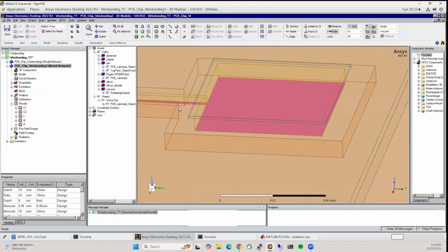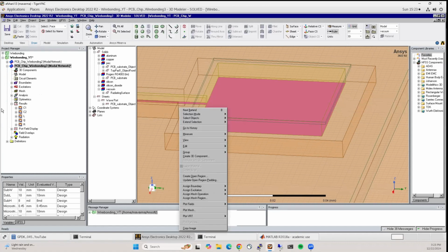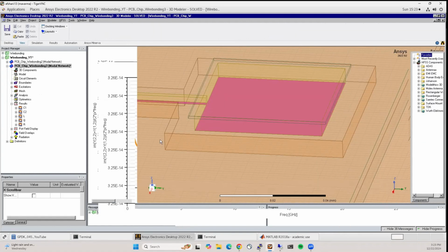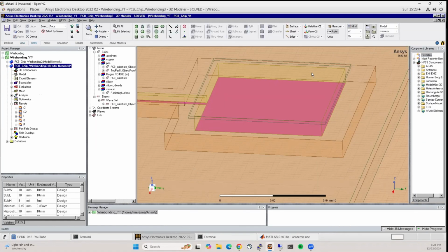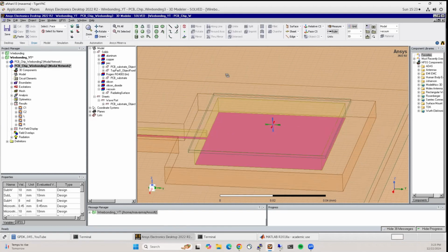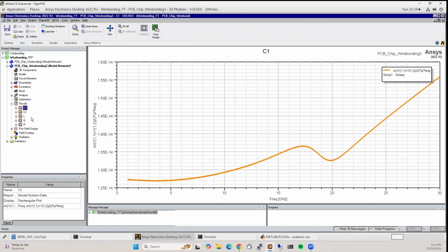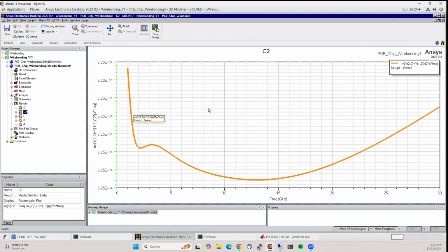Right? And what was the value that we got here? It was around 32. That makes sense, of course, because there's a lot of fringing capacitance to these edges as well. The side, we only calculated this area, whereas the actual area is a little bit bigger than that. So hand calculation makes sense, and also the simulation results make sense. So I think this is sort of reliable, and you can obviously see that C1 and C2 are stable now. They don't go to 0, or they don't go to infinity that rapidly, right?